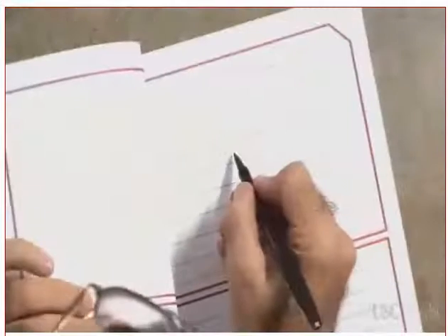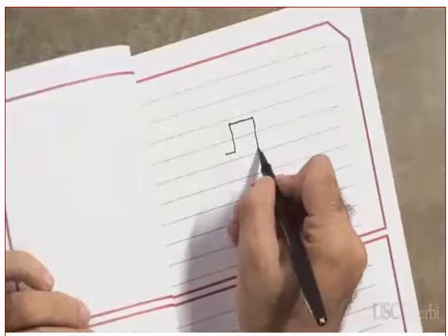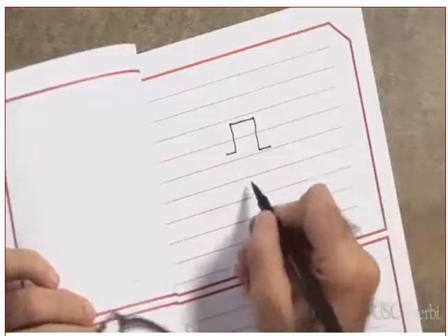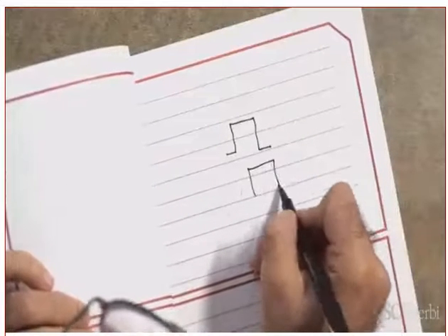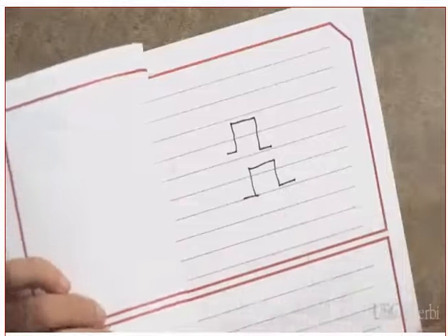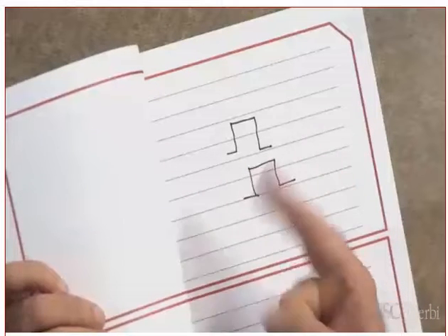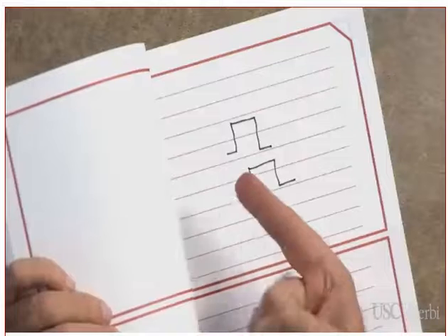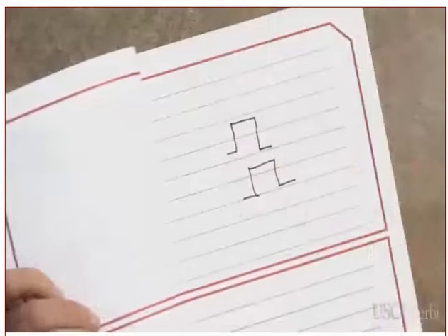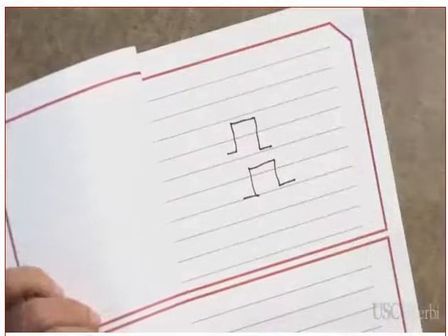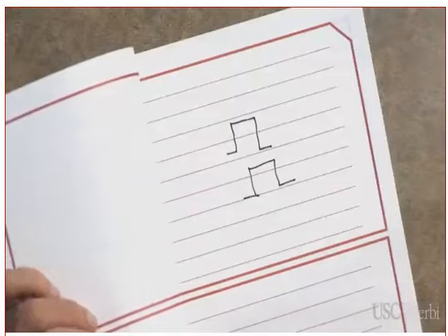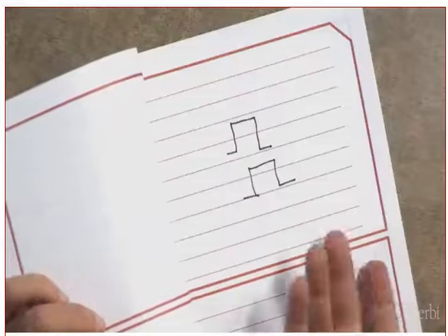Look at this. This is a pulse. Listen to me. If this is the input, and if I get the output here, was there a delay? But was there a smearing in the pulse? There was no smearing in the pulse. What does that imply? There was no phase distortion. There was a constant delay. Every single frequency component at the input got delayed by the same value. Did you understand that or not?